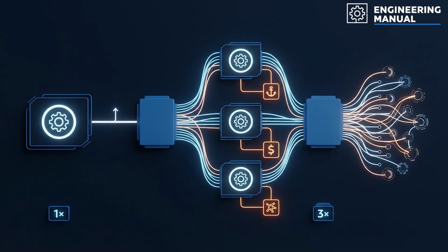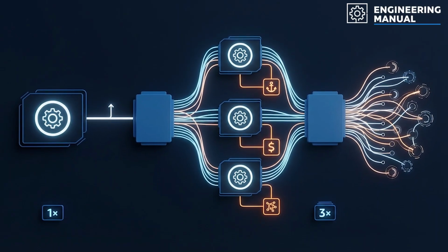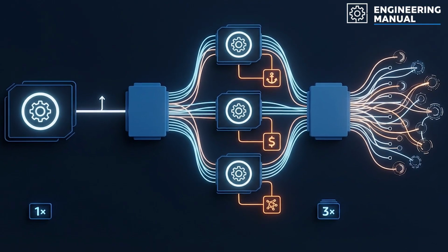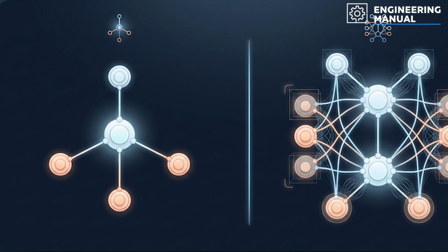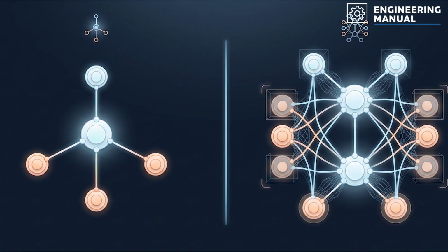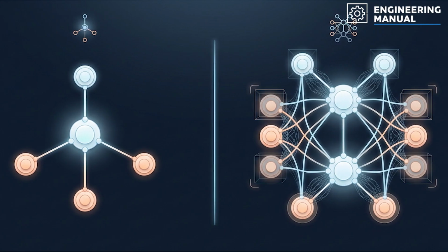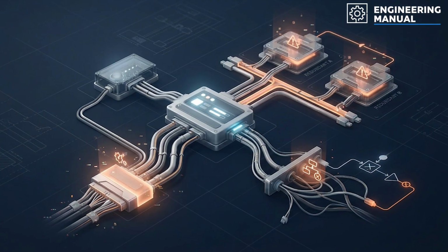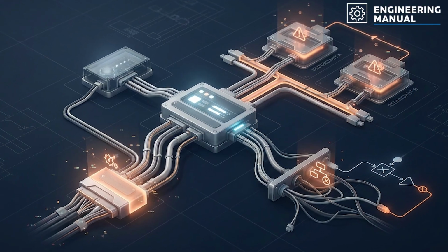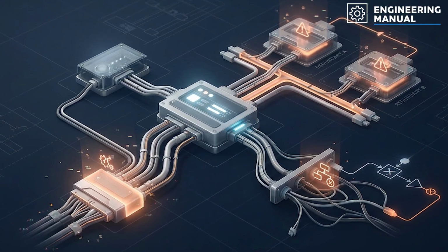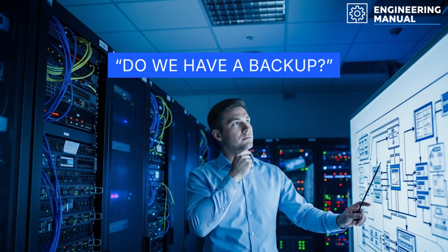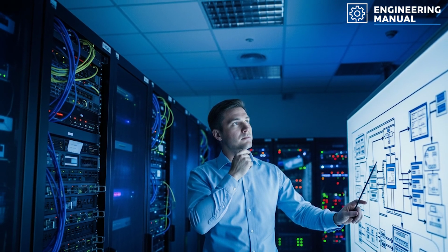At the same time, redundancy is not automatically beneficial. Extra components add weight, costs, complexity, and interfaces, and every new interface can become a new failure point. More wiring, more connectors, more software logic, and more control paths can all create new problems. There is also the issue of common cause failure, where multiple supposedly redundant elements fail for the same underlying reason. So engineers have to ask a harder question than just, do we have a backup? They have to ask whether the backup is truly independent.